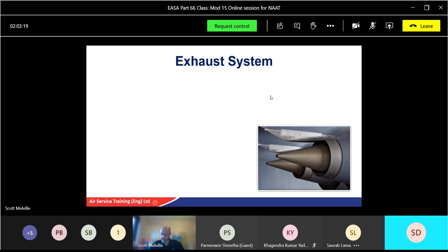All right. Well, how do we fit the turbine blades to a disc? What was the type of fitting? Fir-tree, yeah, fir-tree root, good. And what do we call the type of steel? What range does it come from for the hot environment? The high resistant alloy steel was a certain name we call it. Nimonic range, yeah. You will get Nimonic locking wire, I've mentioned before, to lock and tighten bolts within the hot system as well. So Nimonic range, very high temperature resistant.